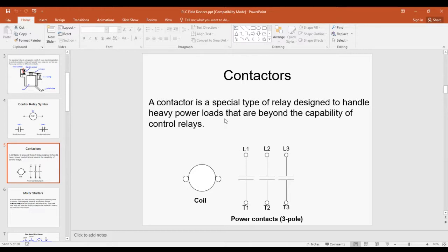Because when they actually transmit AC power from the generator, when you're driving down the highway and you see those big, huge electrical towers strung over, say, a cornfield or something, that's three-phase power. And so AC is way more efficient than DC to transmit. Three-phase AC is even more efficient to transmit. So one reason for three-phase AC is efficiency. And the other reason is that some AC motors, large motors, are easier to start with three-phase than single-phase.